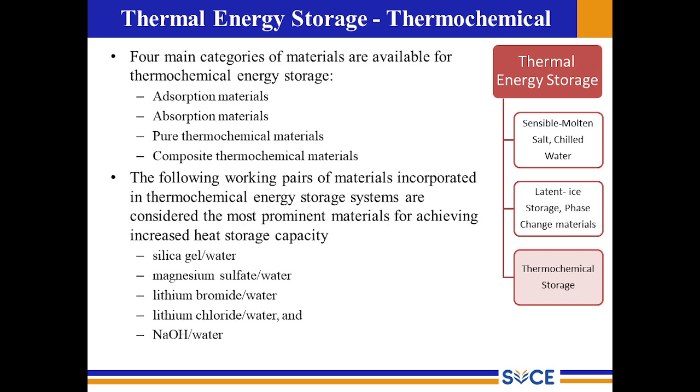You have four categories of materials which support thermochemical energy storage: adsorption materials, absorption materials, pure thermochemical materials, and the last one is composite thermochemical materials. The reaction pairs which are generally used are silica gel-water, magnesium sulfate-water, lithium bromide-water, lithium chloride-water, and the last one is sodium hydroxide-water systems.